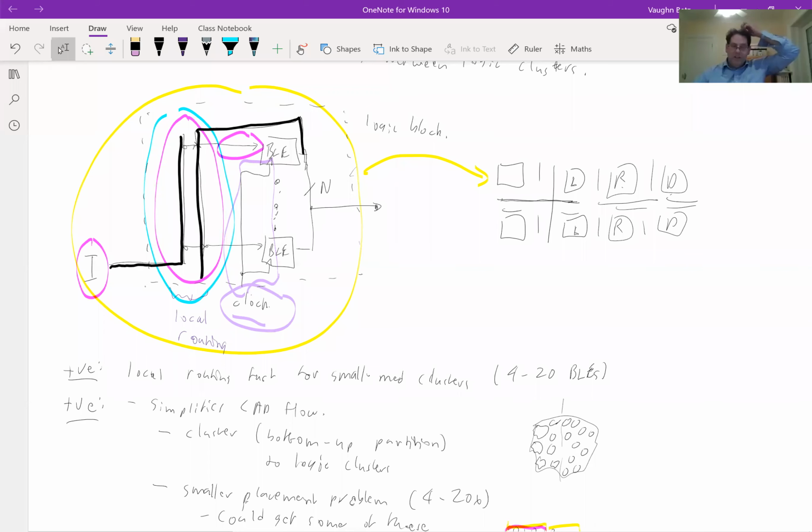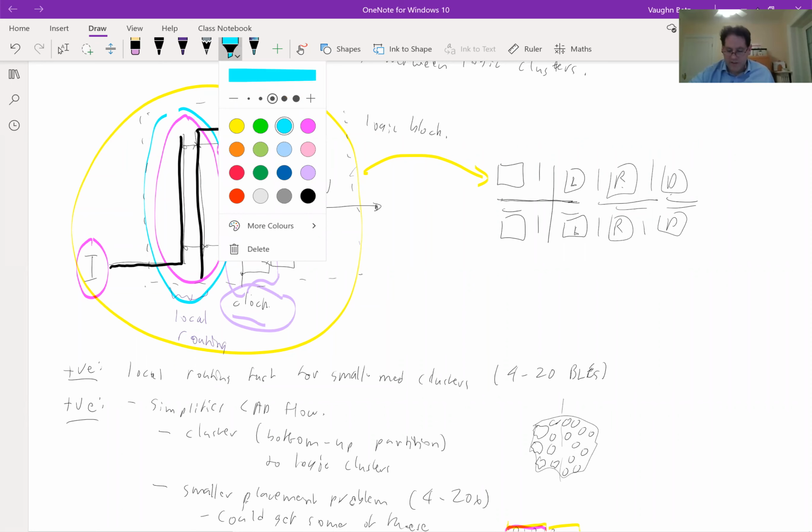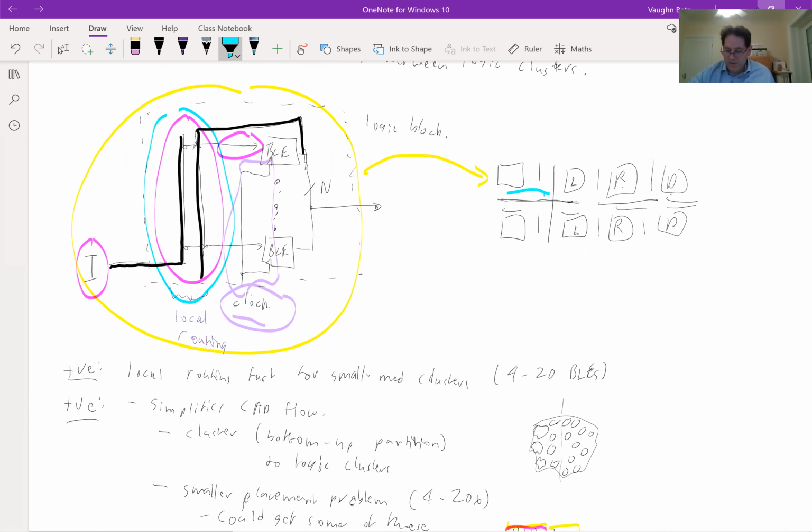In their latest chips, which we'll read papers on towards the end of the course, Intel is making their local routing less regular because of increasing R and C. And Xilinx is making their logic clusters bigger and more regular because they say they need bigger clusters so that there's less pressure on the general island style routing that goes in between them. So it's kind of interesting.